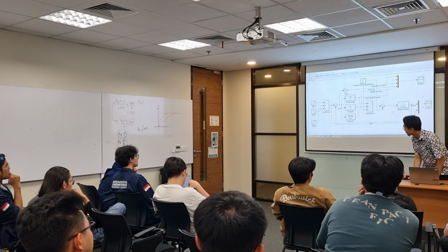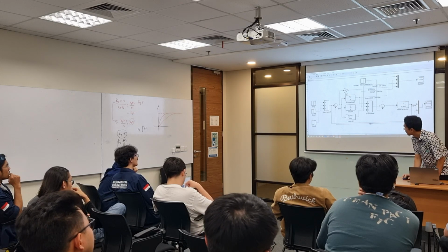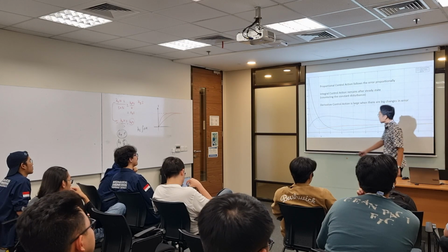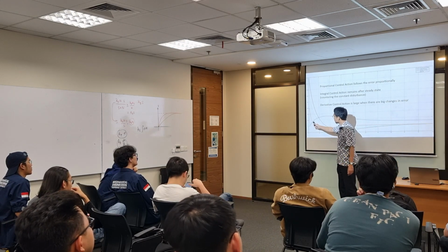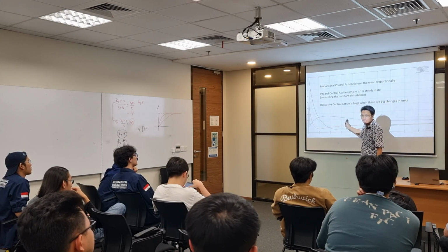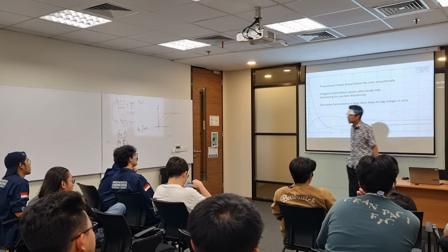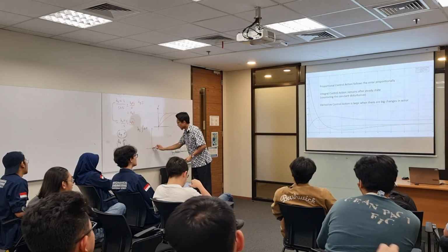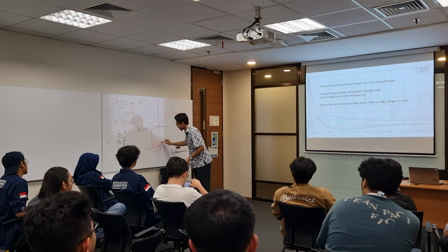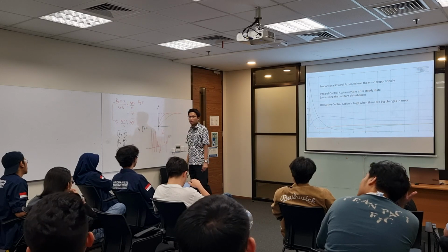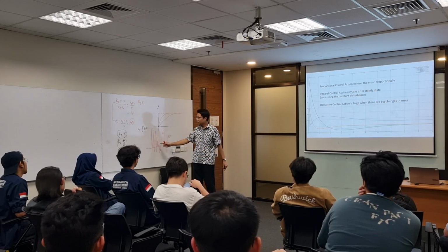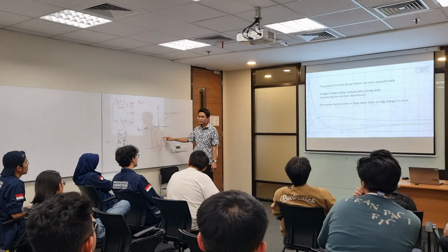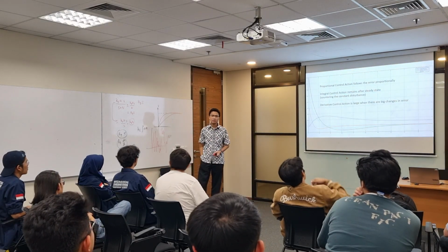You see here, the integral control response is very, very slow. Can you imagine if the input goes like this? Integral control will not be able to catch up with this kind of changes. Cannot. So in this kind of case, you use PD control only.